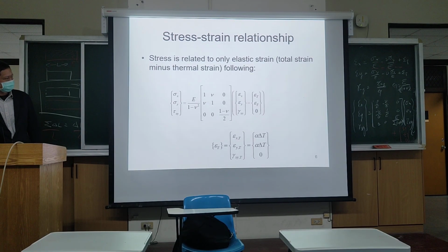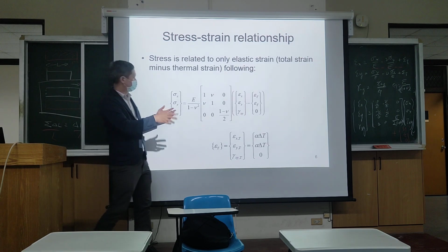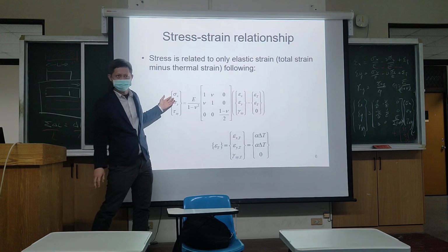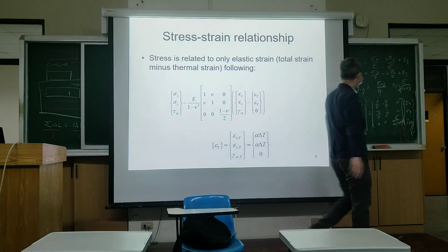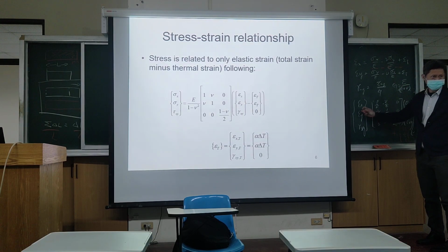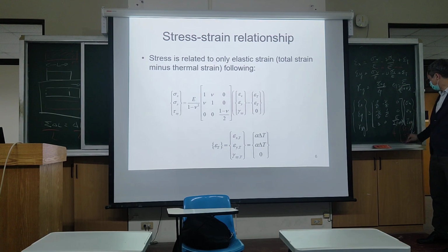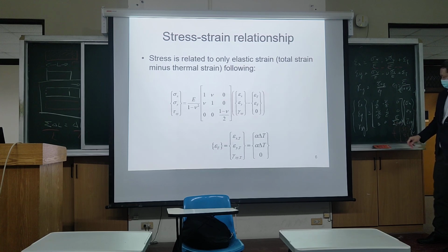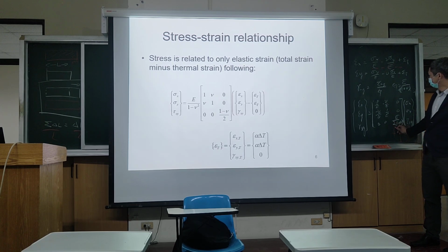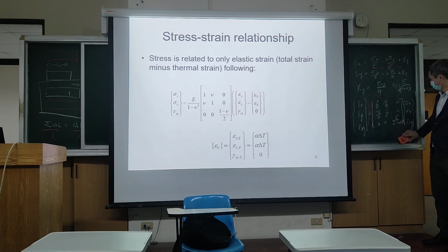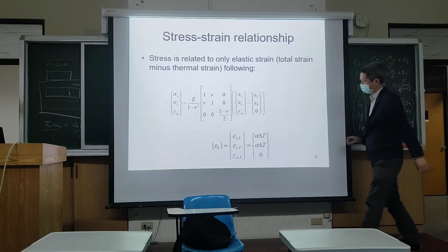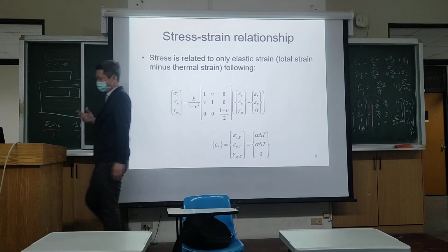Okay. So next, how am I going to re-express the stress strain relation? Okay, you can see here the left hand side is the mechanically induced strain. On the right hand side, you have one thermally induced strain. Since they are strains, why not we shift it there? So then you have minus epsilon T minus epsilon T on the left hand side, all together. Now you can do the inverse.